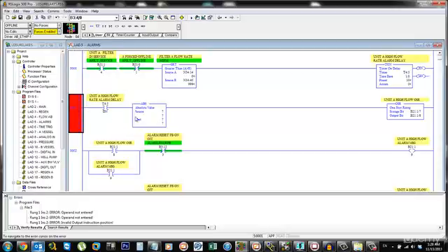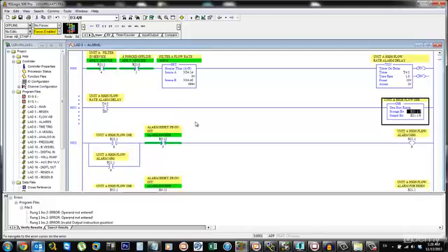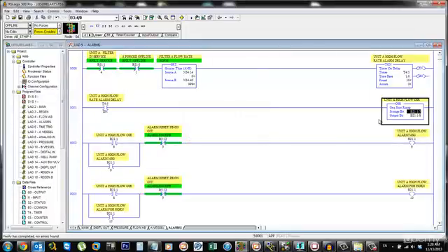On Rung 1, that absolute value block that I added has no source and no destination, and it's not in the appropriate location on the rung that it should be. Therefore, the program kicked it back to me. It won't compile this and it won't load this. When I take that out, I verify my project again.